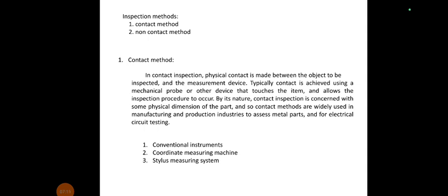In this contact inspection method, today, coordinate measuring machines are computer controlled. The operation of the machine is similar to a numerical control machine tool in which the movement of the measuring probe is either tape controlled or computer controlled. Programs and coordinate data can be downloaded from a central computer, much in the manner of direct numerical control. Also similar to DNC, direct numerical control, is the capability to transmit data from the CMM back to the host computer.